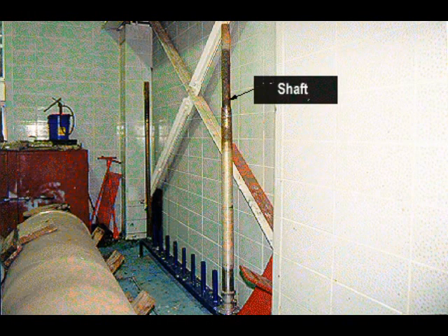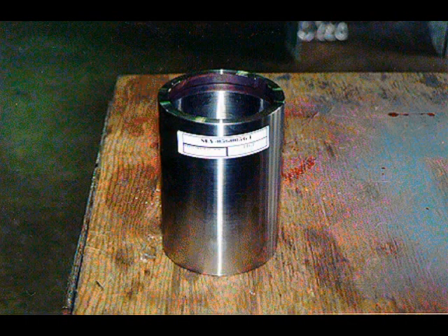Shafts should be stored on end. If laid on a flat surface, the small bumps of the flat surface could warp the shaft. The shaft sleeves are designed to protect the shaft from erosion, corrosion, and wear at the packing box, bearings, and other areas. The shaft sleeve most frequently encountered is the one installed for the protection of the shaft in the packing box. There are various types of shaft sleeves.